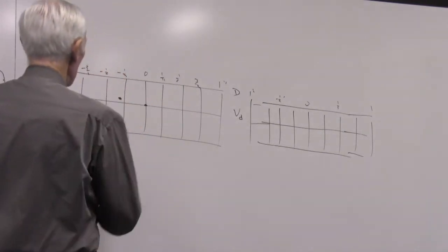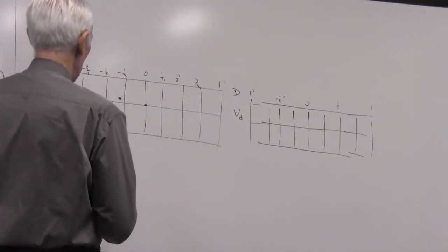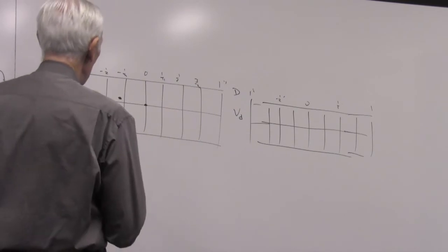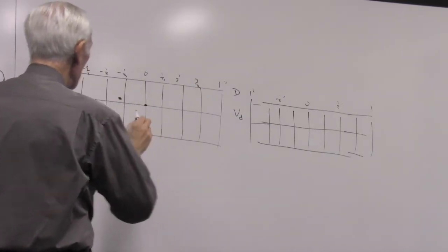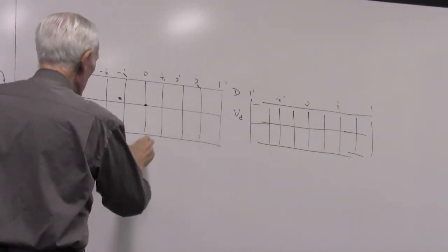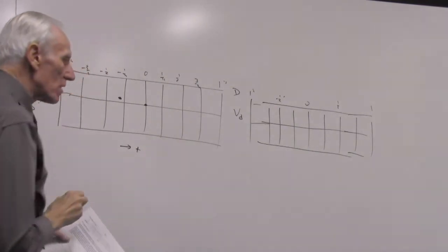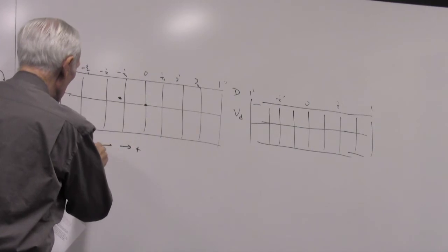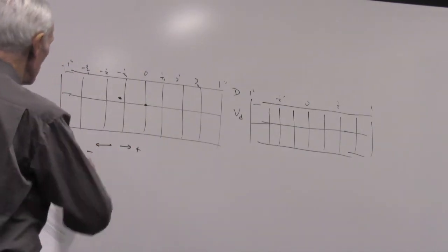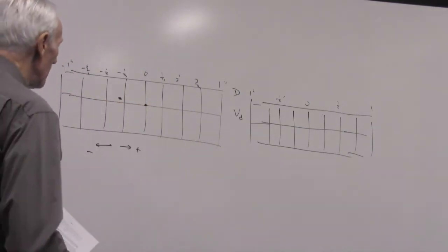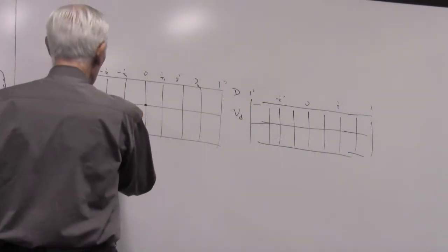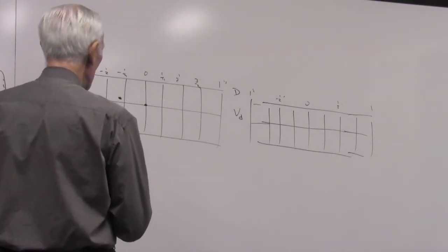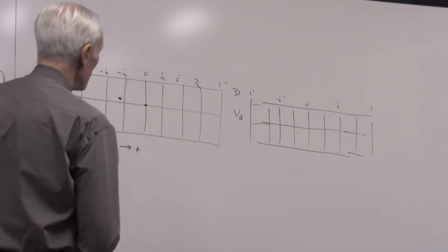Okay, so when you turn the tube on, the dot's going to be there. So it's not on a line, and so you're going to need to apply a voltage. If you apply a voltage to move that dot to the right, we're going to call it a positive voltage. If you apply a voltage to move the dot to the left, we're going to call it a negative voltage. This is like the x-axis here. So it's going to take some voltage to move this dot over to this line, and it's already below 0, so to speak.